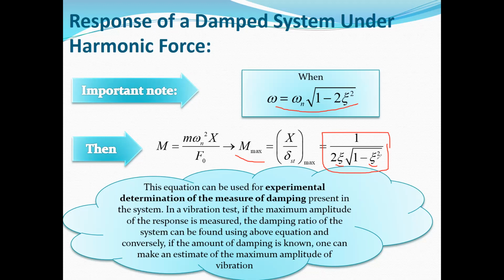So you should analyze your system inversely. Here in this course, when you want to analyze a system analytically, you need to obtain the equation of motion, then solve it and obtain the response. But in the real world, most of the time you have the response, the behavior of your displacement, velocity or acceleration, but you don't have any information about the stiffness, the damping, or the mass of your system.